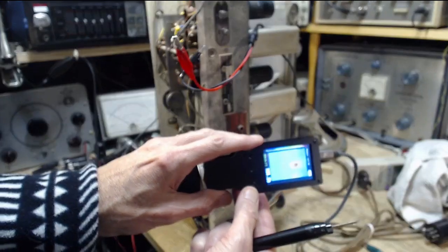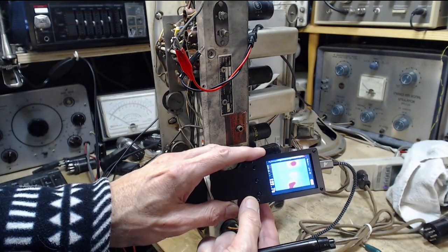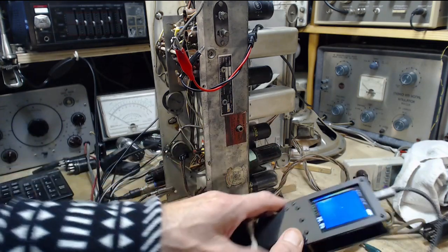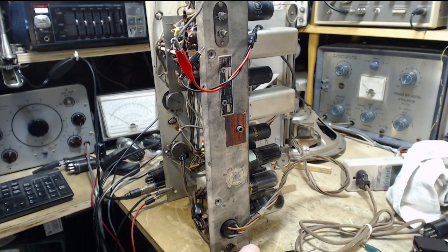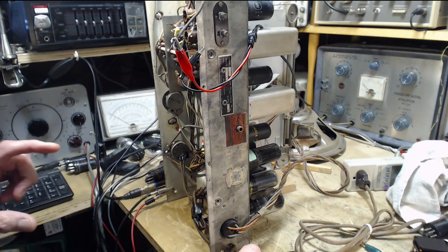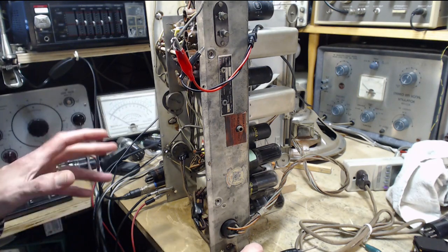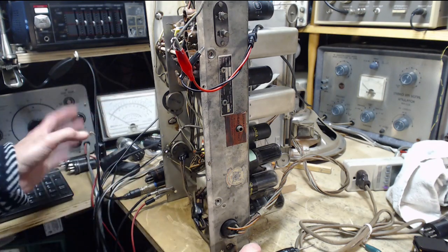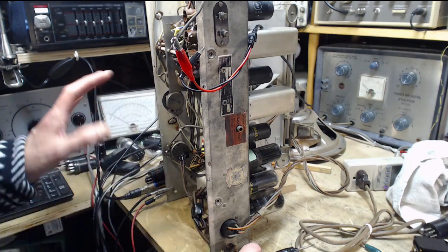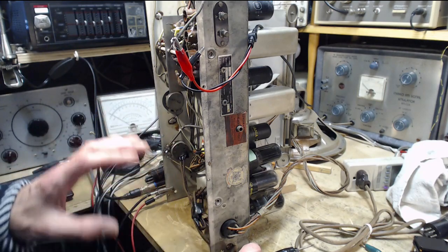That's really not intuitive, is it? Yeah, definitely. So definitely this tube is running hotter. Why in the heck would that be, exactly? The plates get their voltage right from the output transformer. They really can't. Defective output transformer?